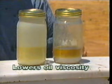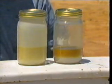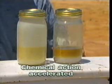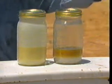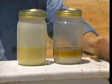Heat lowers the viscosity of oil, allowing the water droplets to settle out more easily and quickly. And heat speeds up chemical action. Chemicals make the film surrounding the water droplets rigid. As heat is applied, the water droplets expand, breaking this film. The water droplets can then merge into larger ones and settle out.